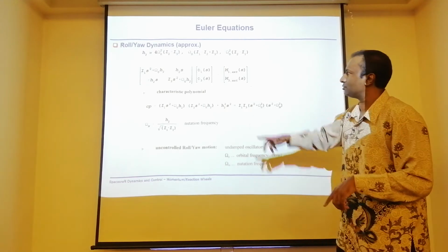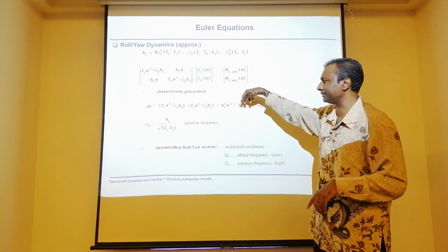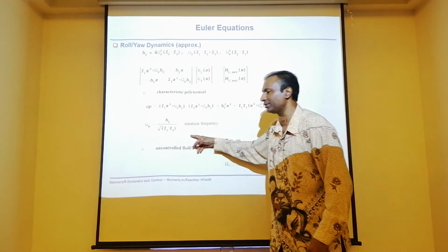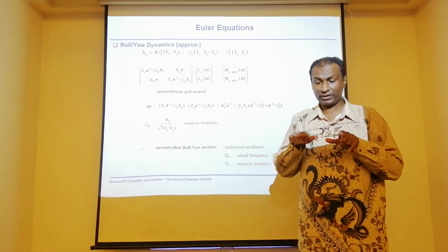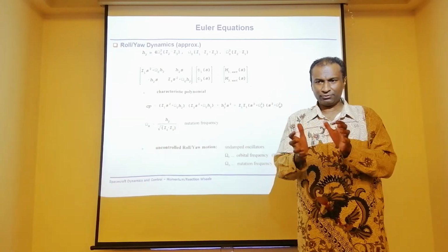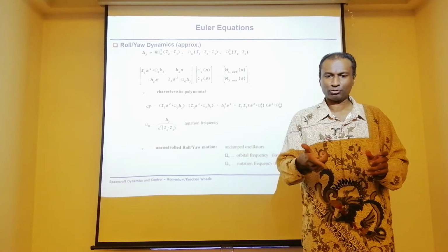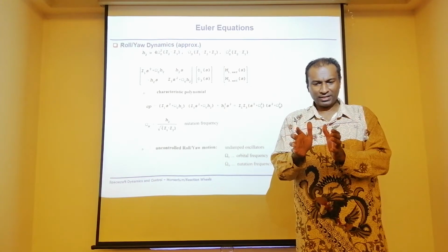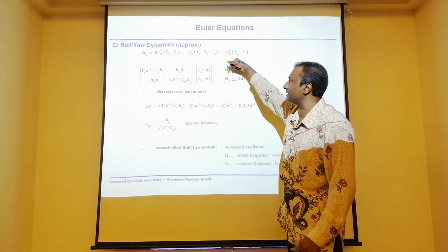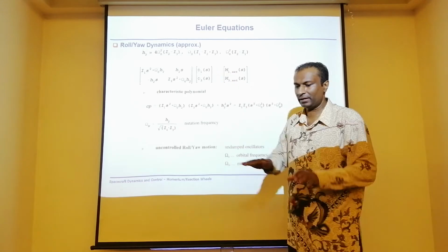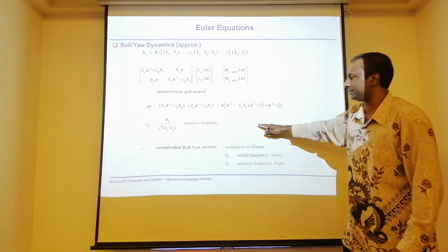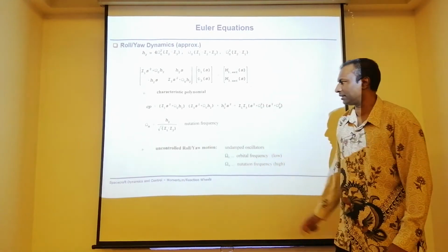Okay, gyroscopic stiffness. So when we do an analysis, it seems that it produces slightly a nutation. There is some nutation frequency. Why is nutation frequency there? Because when you produce a stiffness, this is stiff. If you throw a top spinning at high speed, you can see it is not just stiff like that. It may produce a wobble like this. So that means the two other axes, roll and yaw, might also have a bit of nutation. Okay? So the nutation frequency can be calculated.